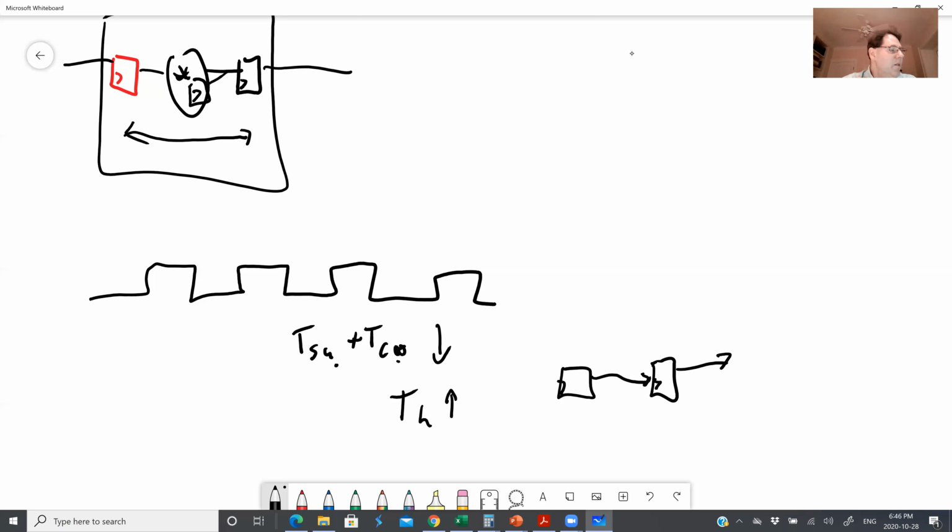This is where the fact that you have this FPGA routing that's relatively slow becomes helpful. If this is too fast, you can tell the FPGA router to basically put an extra wire in. So go up here, go through a routing mux, come back down, now go in here. And that increase in delay hopefully resolves your hold time violation.